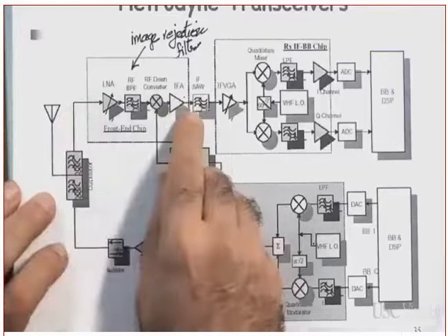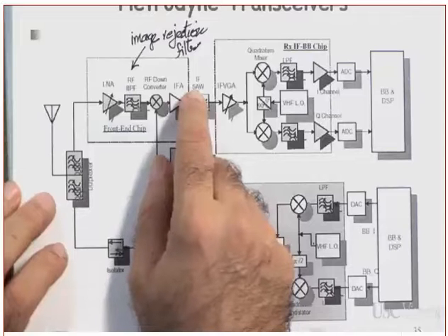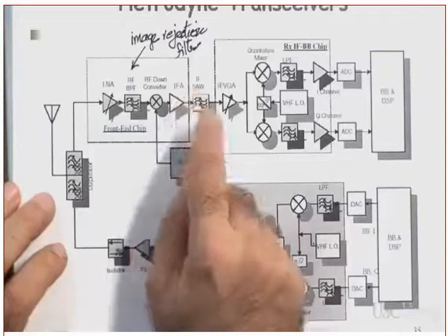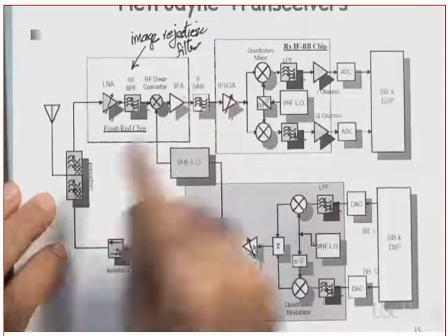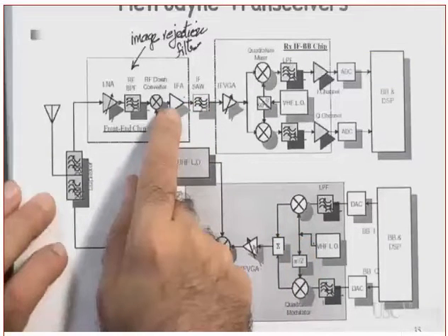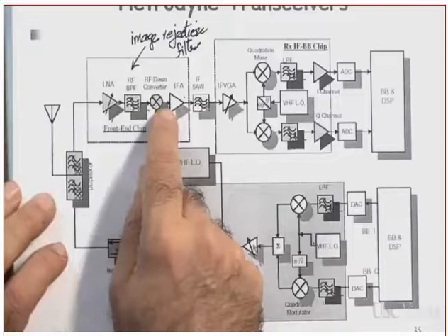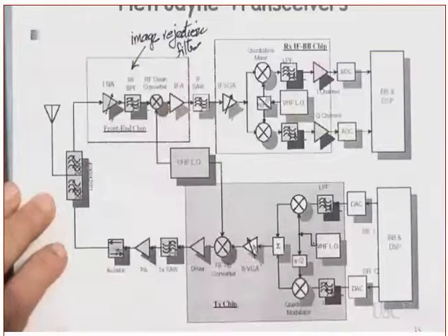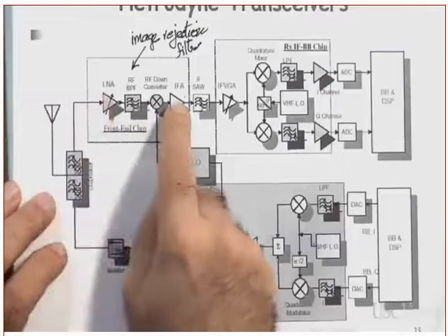Okay, as I will show you in just a second. What is this one doing? Anybody saw? Surface acoustic waves. Those are bulky filters. Bulky filters, most of the time, are off the chip. Clear? What is, by the way, IFA? IF amplifier. Are you following me on that? Again, remember what I told you last time? You try to distribute the gain across the receiving chain, not only in one block. So we have, for example, the LNA, we have the IFA.